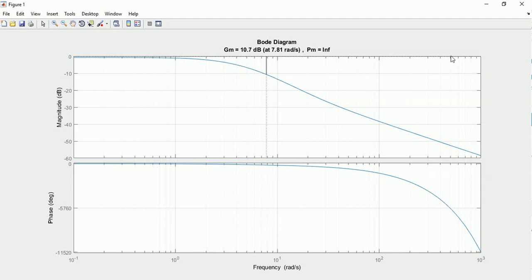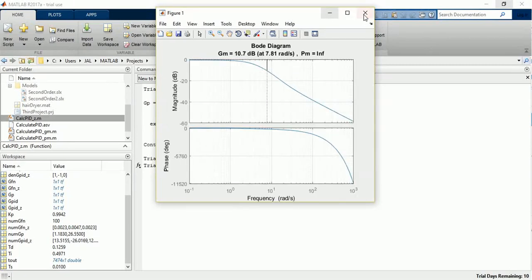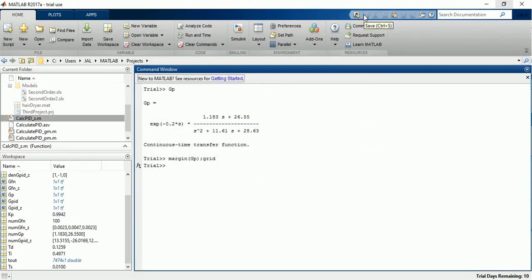And another way to see how this system will work will be by looking at the step response in the closed loop. So imagine that I take just the plant and put a controller, which is just a gain, k equals 1, that's it, and close the loop and implement the controller in order to see more or less what will be the response of this system. And I can do that by using the step instruction of Matlab.